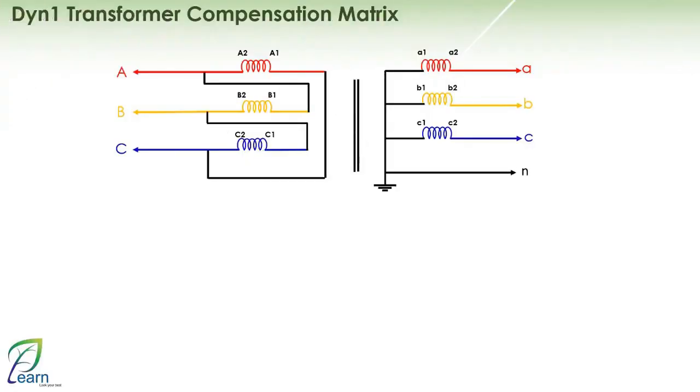Then I go to phase C, where you also have the presence of an external single-phase fault, and the current drawn in this direction will also draw from the phase C winding. Consequently, it will be drawn from the phase C cable through the winding and return from phase B. This means that the current of phase C on the star side will draw a corresponding current of phase C at a 0-degree angle on the delta side, and the current of phase B will also be at a 180-degree angle on the delta side.